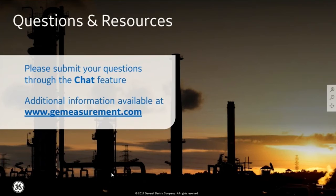Okay. Yeah, great. We also have, Matt, a couple of questions about wedge delay calibration, a request to see wedge delay, and then also any reason that we didn't show it. So can you talk a little bit about wedge delay calibration? Yeah, sure. So for today, we were demonstrating the concept, and so we took out some of the steps. We also didn't do a TCG and sensitivity cal and some of the other steps that you would commonly do, really just in the spirit of time.